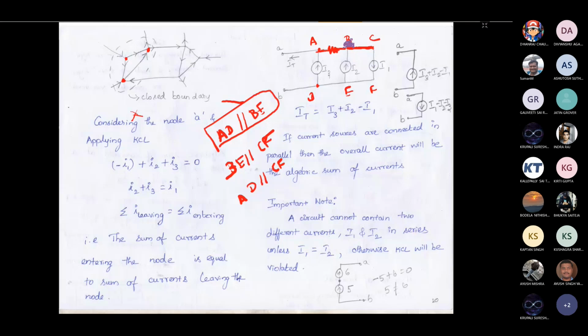So let's move back and consider that there is no resistor and you have the actual circuit like this. Then these current sources are in parallel. If they are in parallel, you can consider the summation of the currents: this is in upward direction, this is also in upward direction, and this is in downward direction. You can represent that as an equivalent current source like this.